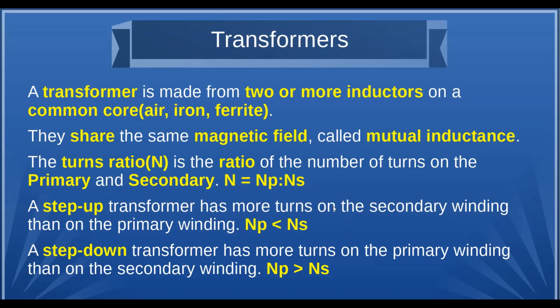However, when I do that, whatever current I have on the primary is going to be halved on the secondary because the power into the transformer, assuming no loss, is going to be the same on the output. So whatever the input power is, the output power is going to be the same, even though the voltage and current will be different. So you're going to run, let's say, 120 in at 100 amps, and then coming out, it would be 240, 50 amps. If that math is right. Well, yeah, depending on what you're doing.